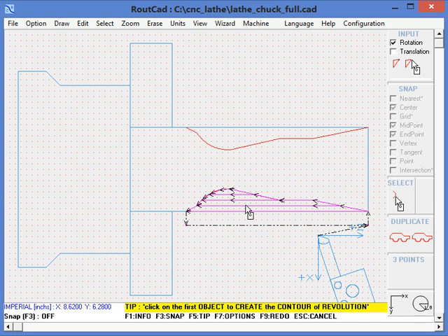What we have specified was only roughing passes with half an inch clearance, with 0.2 inch for each roughing pass. And in this case, this is the very first roughing pass, which barely touched the material. The second goes in, the third, the fourth. Basically, there will be 5 passes. 1, 2, 3, 4, 5. And on the 5th pass, it will completely machine this surface of revolution.